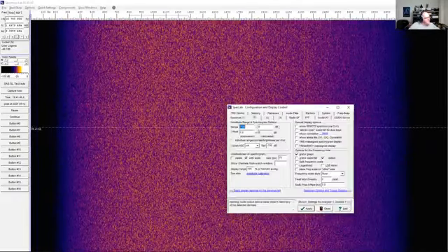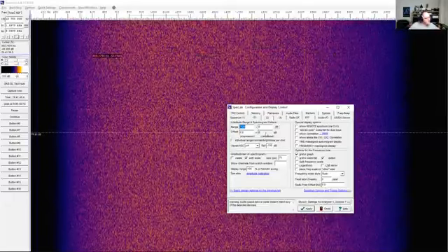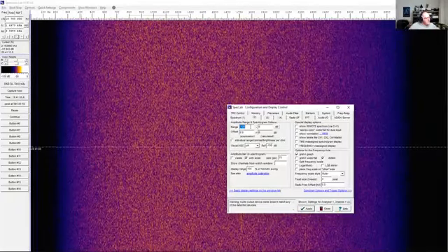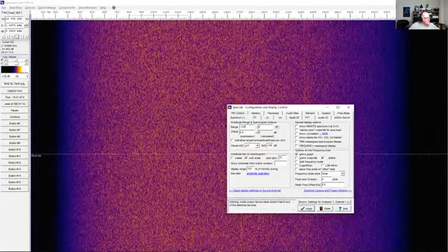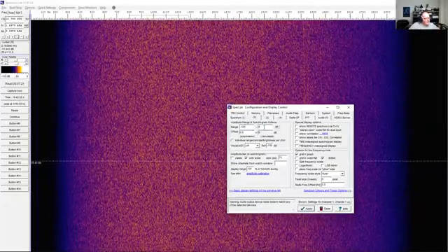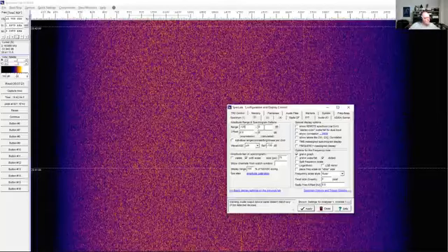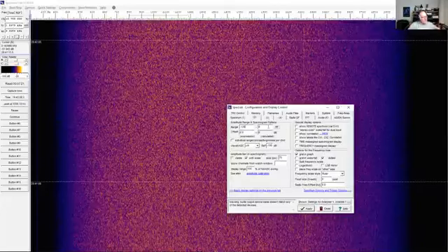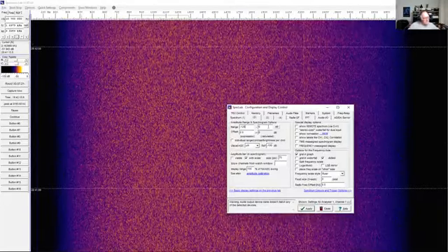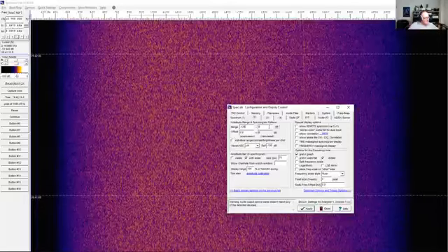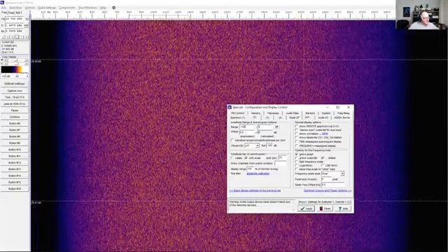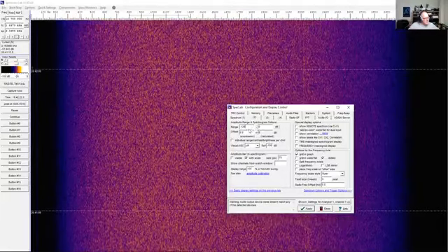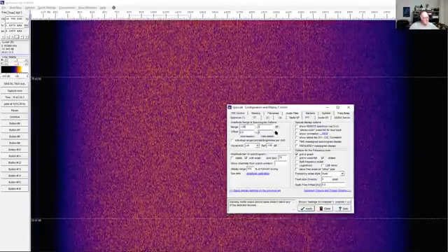So this range of colours that you can see is reflected in this range of gain between 120 and 0 dB. Now, it's unlikely we're going to get a really strong signal that would go all the way down to 0 dB. Okay, so again, if I pull that plot screen, we're not going to get something which is going to leap off there, well, highly unlikely. But because we've got minus 120 and 0, we've got potentially 120 divisions of sensitivity that we can see.